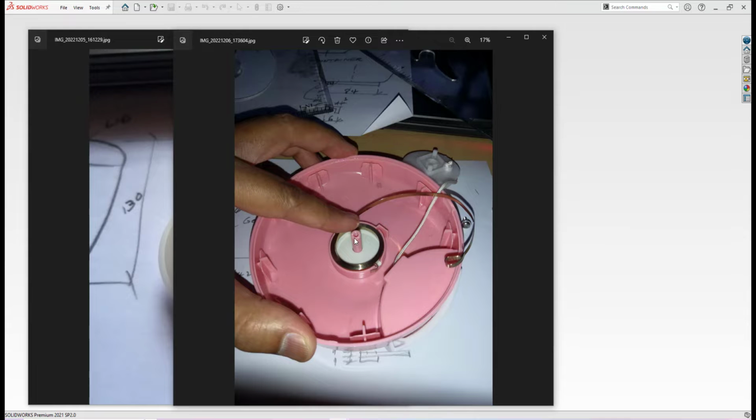So the idea of having this flat coil spring is that when we pull the handle, the handle will rotate the pulley and also rotate the blades, but the coil spring has the energy to push back this handle and also this rope to its initial position. So that's why they have a coil spring.